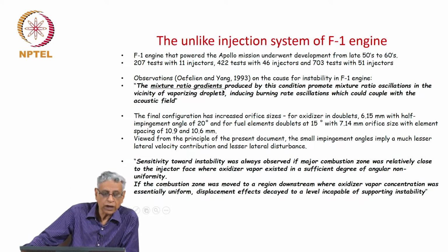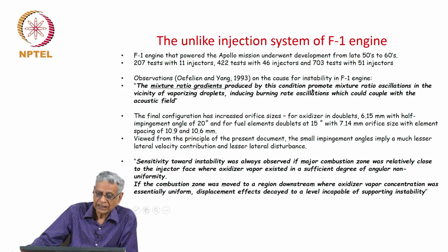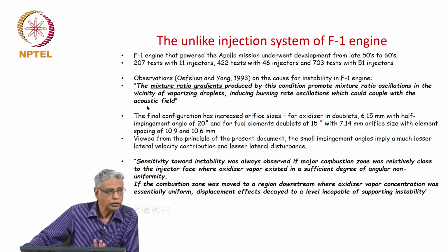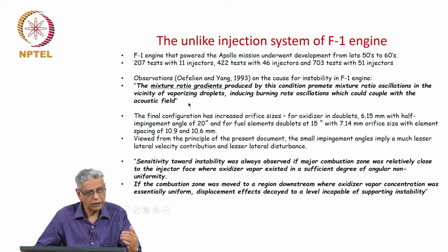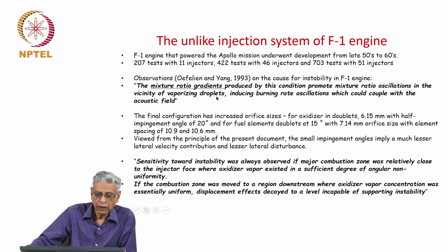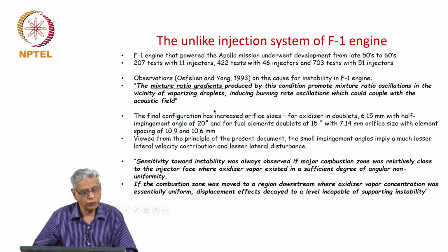The mixture ratio gradients produced by this condition of the injection system promote mixture ratio oscillations in the vicinity of vaporizing droplets, inducing burning rate oscillations, which could couple with the acoustic field. Exactly the kind of point which I made a few moments ago. You are vaporizing droplets, and the acoustic oscillations interact with burning rate oscillations, and the coupling produces the instability.